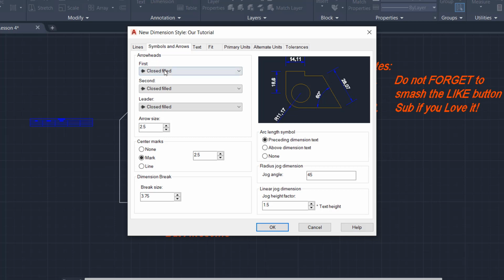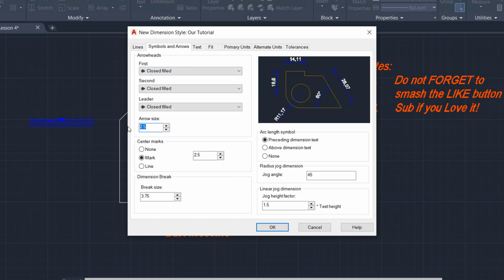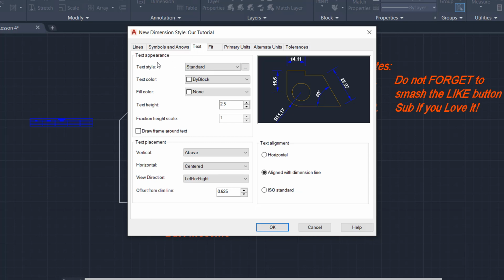As you can see, you can change arrowheads. In practice, different arrowheads are used for different purposes like architectural, mechanical, structural, and etc. Then we have arrow size. Change it to 3.5. Center marks, it puts a mark at the center. You don't want that. And others should stay as they are. I will make another video for them if needed, of course, because they aren't used much. Let's go to a text.